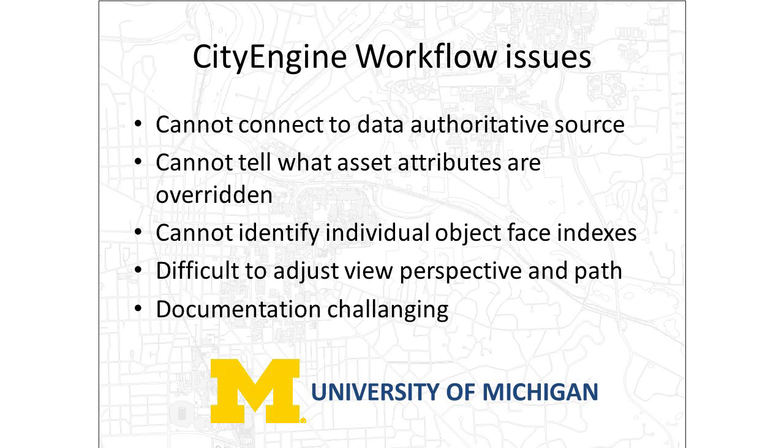If we update the data, what we try to do is an SQL update of the file geodatabase, because if we remove the file geodatabase and put a new one in, then you have to reattach the rules to the objects. So it's painful in that respect. Because of the bug in 2015, what you end up having to do is go out to a shapefile. You can either leave it as a shapefile or convert the shapefile back to a file geodatabase and then attach to that. So yes, it's a big limitation.